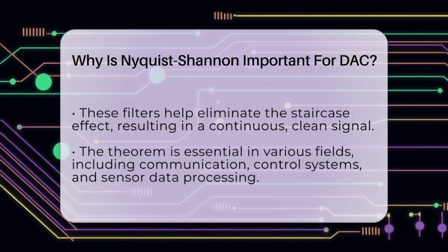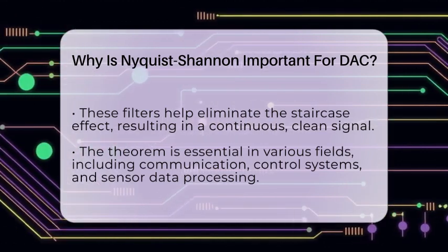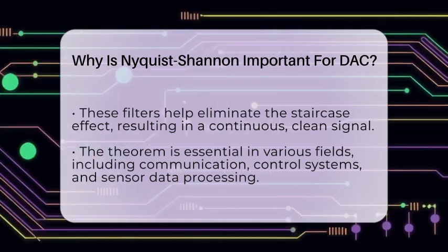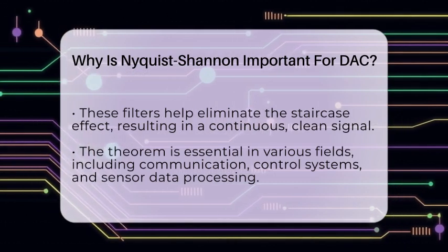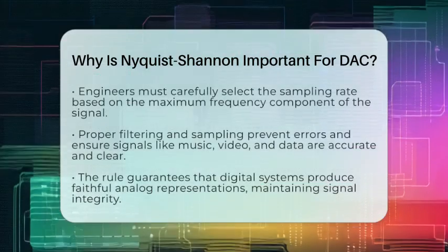The importance of the Nyquist-Shannon theorem extends beyond audio. It's vital in communication systems, control systems, and any place where digital signals are converted to analog. If the sampling rate is too low, the system produces distorted signals, which can cause errors or poor performance.